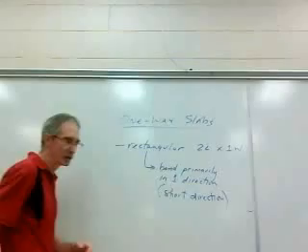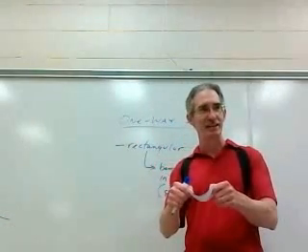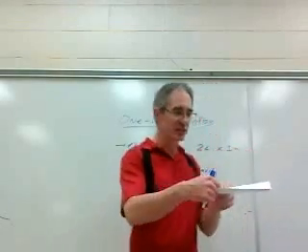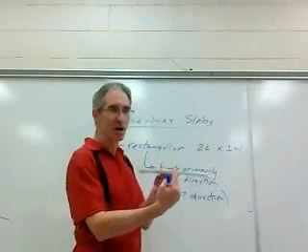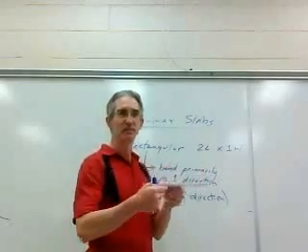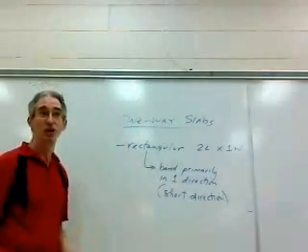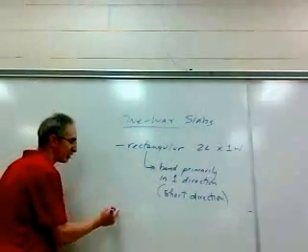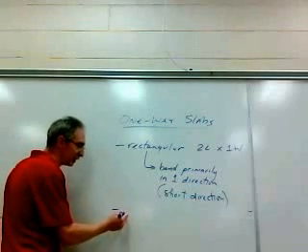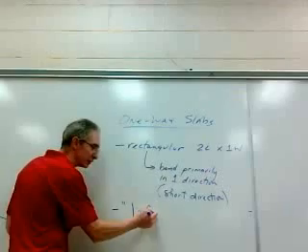One-way slabs, even when you say, hey, it's bending like this, therefore I'm looking at the slab, do I design for the width of the slab being this long? The answer is, well, you could. Generally, you don't. Generally, when you're doing a design or evaluation, you consider for a slab a 1 foot strip.